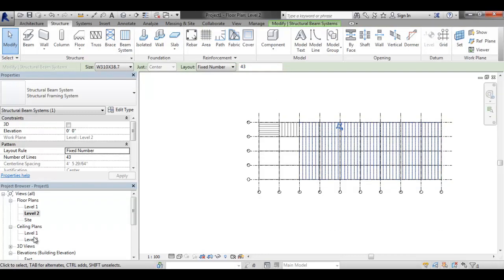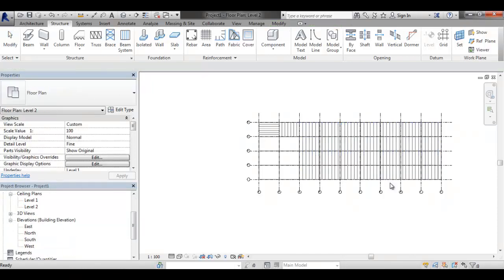Let's go ahead and talk about braces. So when I have a system like this, I need to brace at least one bay. I'm either going to have a concrete core if it's a high-rise, and then I have my stair cores, and that's going to brace for lateral bracing. So anytime we do a brace, it's for lateral load.